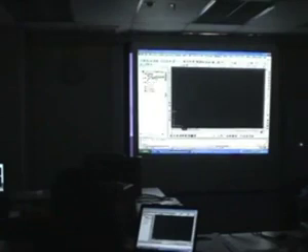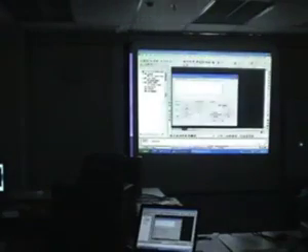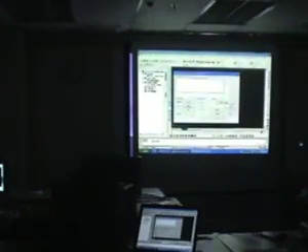And what I'm going to do is extract information from that drawing, because it's possible that drawing may have a lot of other garbage inside. Maybe you've got other contour lines, even other text like words sekolah, rumah, that you don't want to put into your 3D points. So this is the use of query. We're going to use the query to basically filter out the information, to extract certain information from the attached drawing.